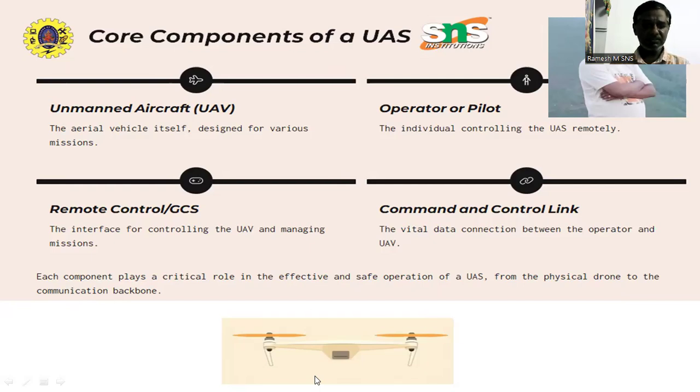One of the most important subsystems within the UAV is the autopilot, which receives the control inputs from the GCS, as well as from the ground, and executes the pre-programmed flight missions. Embedded within the UAV is the navigation and guidance system, typically combining the global positioning system, that is GPS, as well as the inertial navigation system, INS, magnetometers, and barometers, allowing for precise geolocation and flight stability.